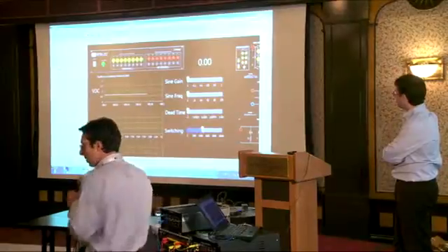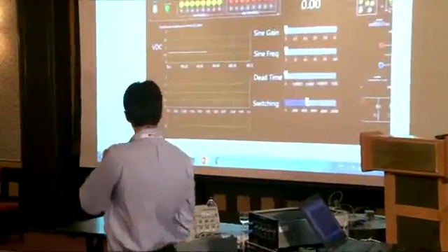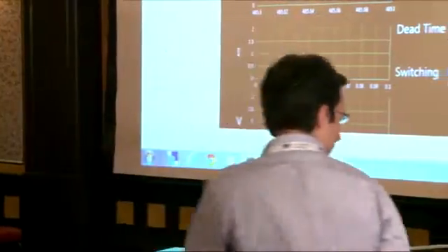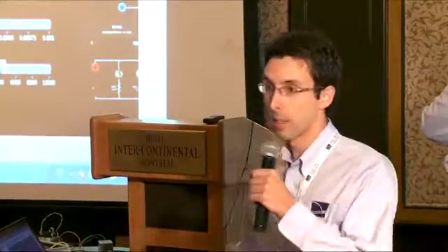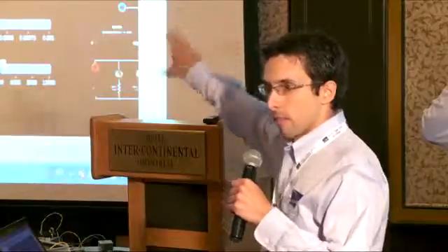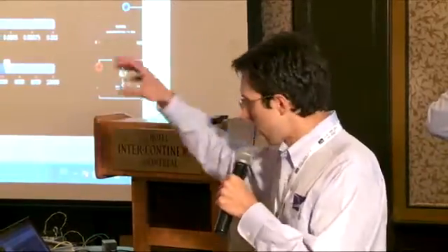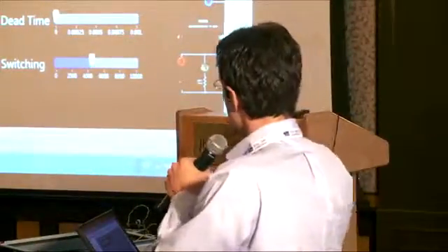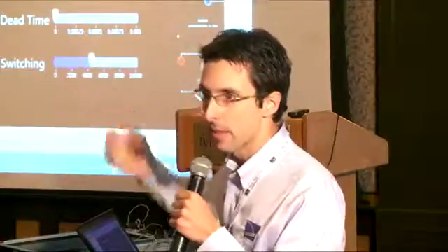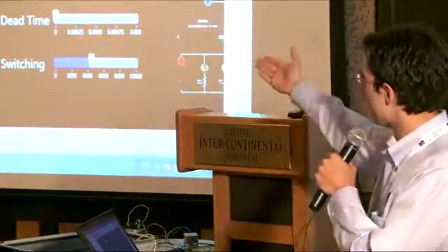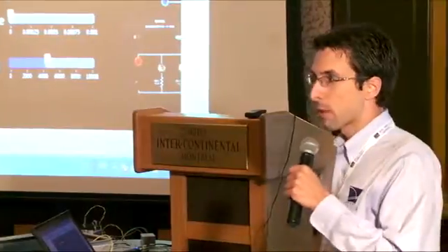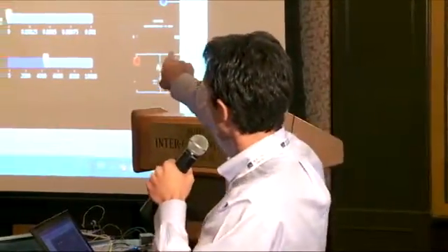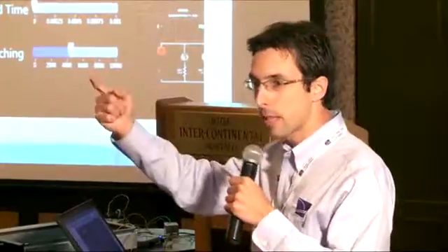So if we do a quick parallel with the EHS that we saw this morning with Pierre-Yves' demonstration, the IO boards that we have here, it's any FPGA firmware that we have flashed on the FPGA. So we can have the EHS board here, which is our real-time power electronics FPGA firmware. We have all the inputs, so we can, for example, take the EHS, okay, I'm going to send the firing pulses to this EHS, and I will take the simulated measurement out of this EHS, route this to a GUI, or route this to another IOs, or connect this to a Simulink controller model.